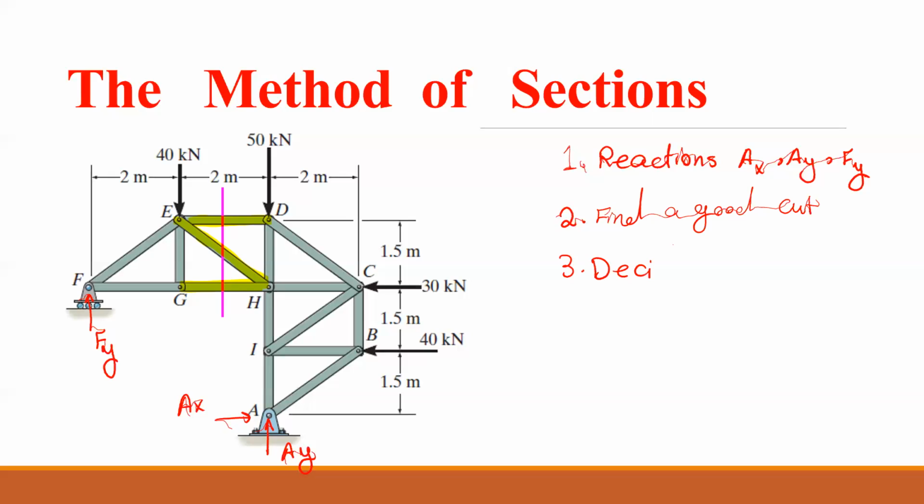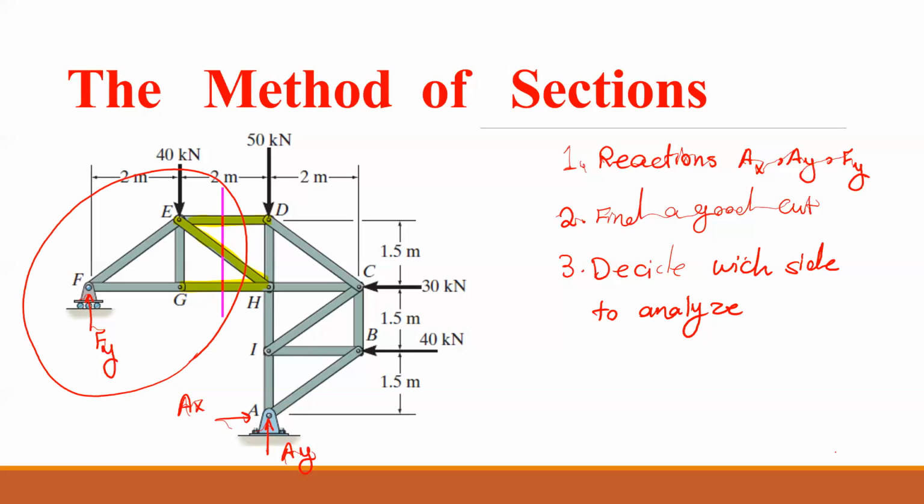to decide which side to analyze. Which side is easier, left side or right side? Okay. The side that is involved with fewer external forces is usually the best part. So this side is the best side to analyze.